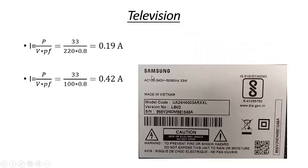Likewise, we have the television. You can see it from here. The range of voltage for the television is 100 volt to 240 volt, and its wattage is 33 watt. For 220 volt, it will draw a current of 0.19 ampere, and for 100 volt, it will draw 0.42 amperes. This is for the television.